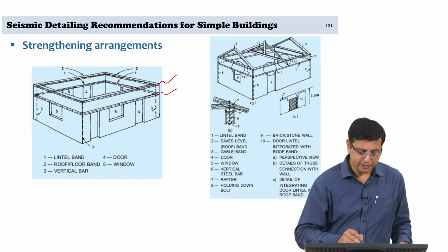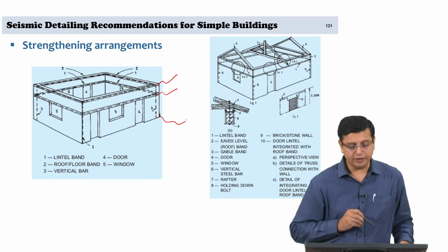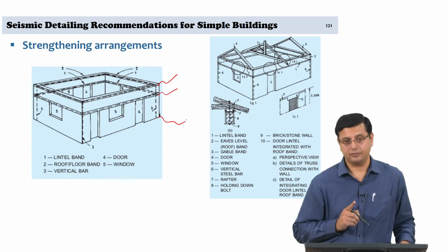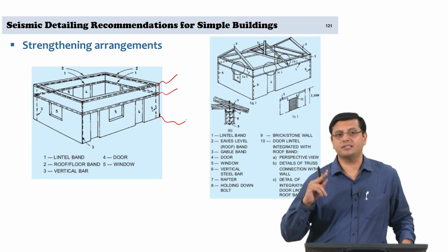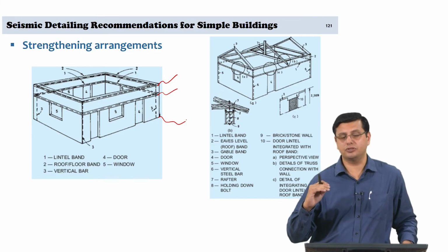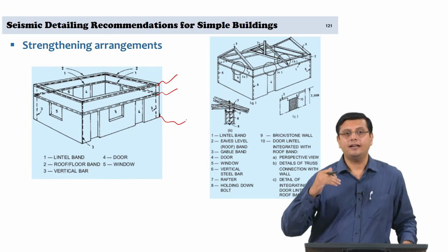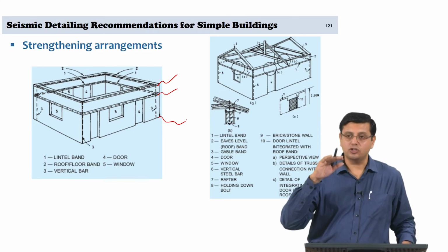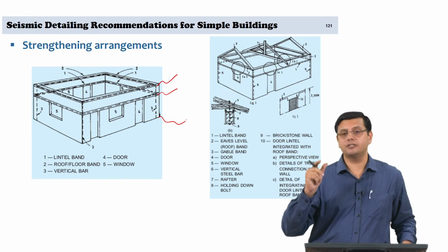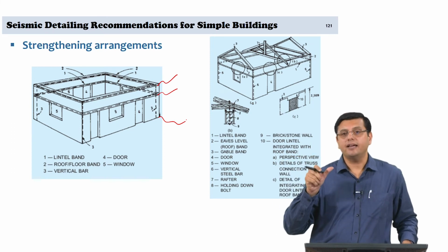A third band is typically prescribed, which is going to be at the plinth level. So, at any point which is a transition zone, an important transition zone, foundation to the resisting wall, at the plinth level you will have the plinth band. As you go to the top of the openings, that is a transition zone merely because